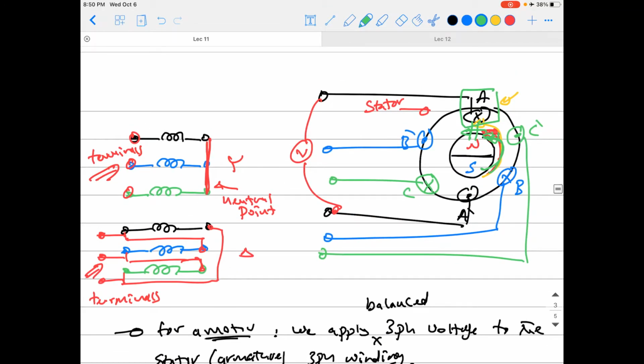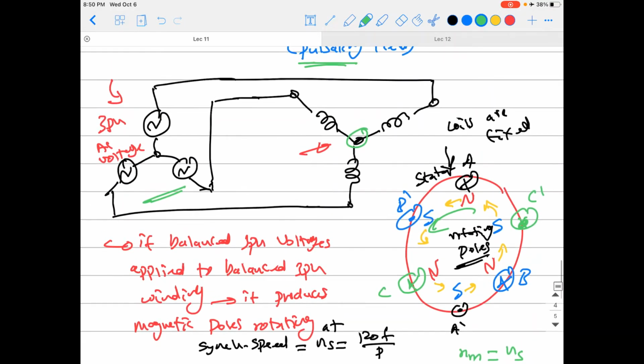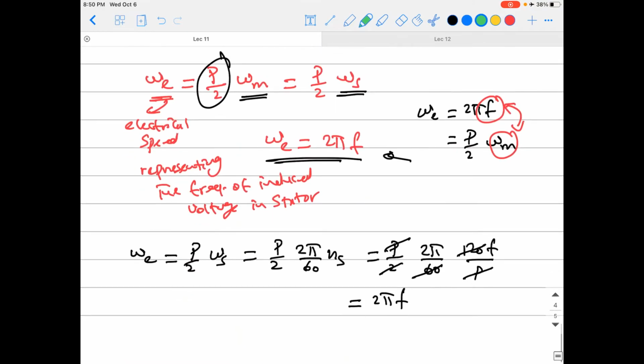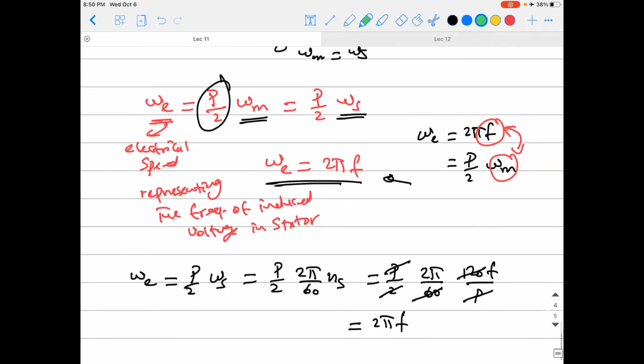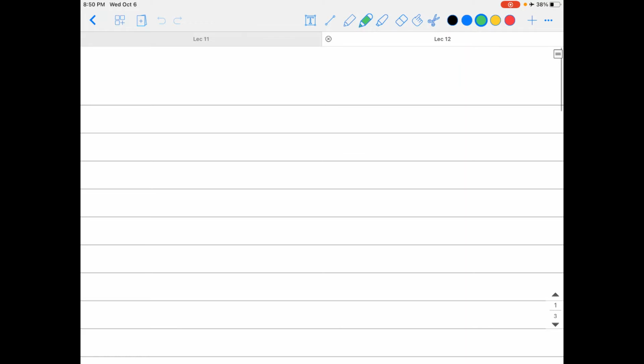So the armature winding is now subjected to a time varying magnetic field coming from the rotor poles, and a sinusoidal voltage will be induced in these coils. Because you have three phases, meaning three separate windings in the stator separated by 120 degrees, you now have a three-phase output voltage from the machine. Like we said last time, the three-phase winding also carries current, and I will try to write those down now.